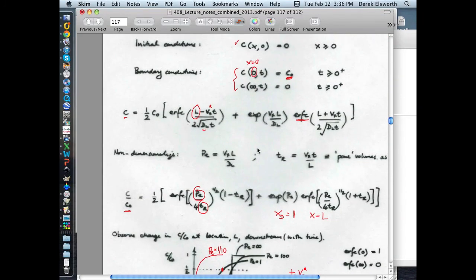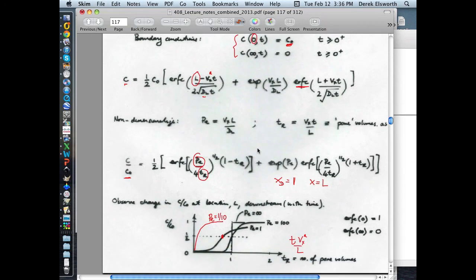So really the important material, the results that are basically on this page, is being able to look at, for instance, this distribution at the compliance point. And of course, if you wanted to, you could choose different lengths. The other thing that you could plot is, for different lengths along the plume, you could choose a length, and you could calculate the concentration at a given time, and you'd get some concentration magnitude here.